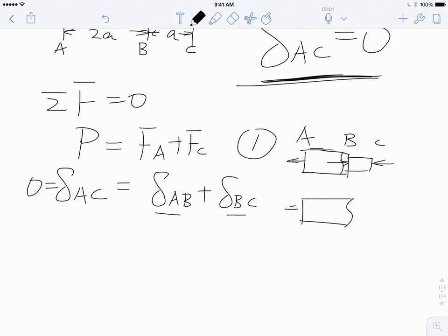And then this force is Fa, I say. Now there has to be another force, which is Fab, the internal force. What is Fab equal to? You guessed it, Fa. It's the same magnitude as Fa, but in a different direction, pointing to the right, because the summation of F has to be 0 for AB as well.